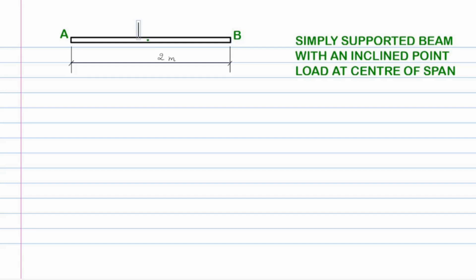center of the beam. As explained in the last lecture, a simply supported beam is in general shown to be supported by one hinge support and one roller support instead of both hinge supports or both roller supports. Let's show the hinge or pin support to our left and the roller support to our right.